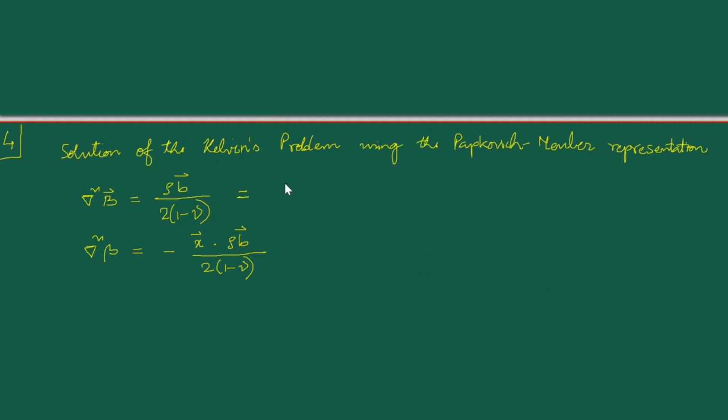In this equation, this rho b vector gets substituted by this p vector. But it is not enough to write it as a p vector, because that would imply that this p vector is acting at any general point within the body. No matter which x vector you choose within the body, this p vector would apply. But that is not the case. That p vector is applied only at the position x vector equal to xi vector. How do we specify that?